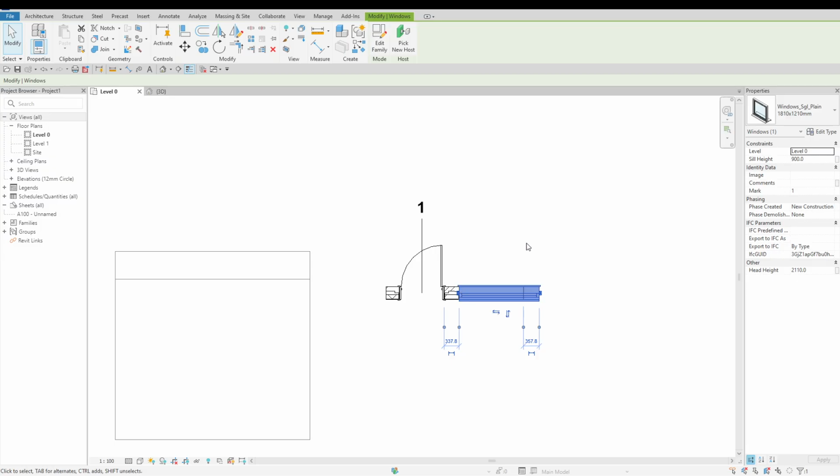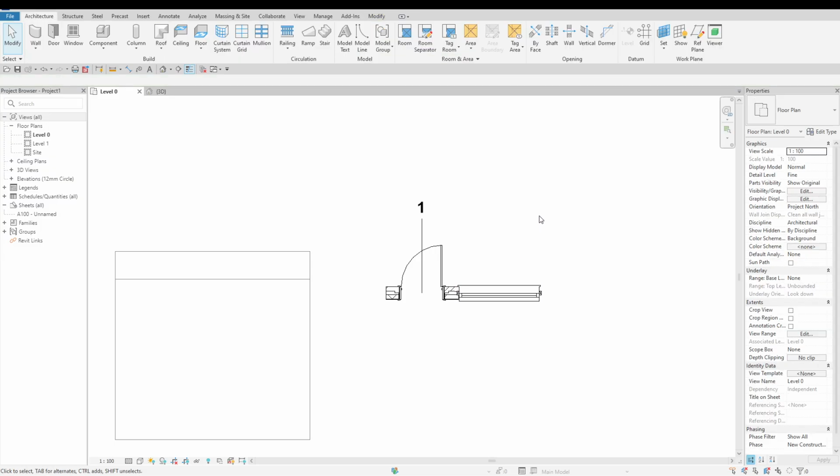Freestanding components are used to model building elements that are typically delivered and installed on site, such as furniture and plumbing fixtures. You can place freestanding components in your building model by following these steps. On the ribbon, click one of the following.